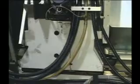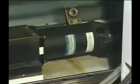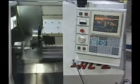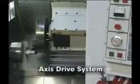Each axis consists of a mechanical component, such as a machine slide that moves, a servo drive motor to supply power for the movement, and a ball screw that transfers the power from the servo drive motor to the mechanical component. These components, along with the computer numerical control functions that direct them, is called an axis drive system.